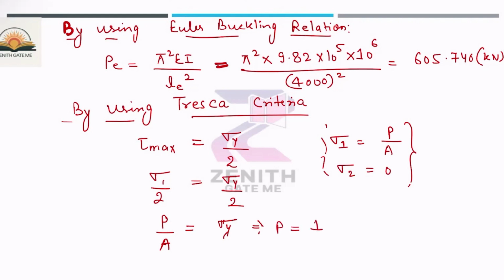σY is given as 145 and the area is given as 7.85 × 10^-3 in meter squared, so it becomes millimeter squared if you multiply by 10^6. Once you solve, you will get the value of 1138.25 kilonewton. You have to calculate how much maximum load it can bear.